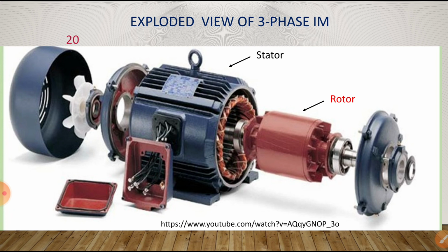And we have seen what is told by Michael Faraday, and what are the different materials used in our electrical machines, and how they are useful to reduce the iron losses in our machines. Generally we have seen that silicon iron alloy, nickel ferrous alloy and cobalt ferrous alloy are used, and nowadays we are using amorphous magnetic materials also in our motors and machines to reduce the iron losses.